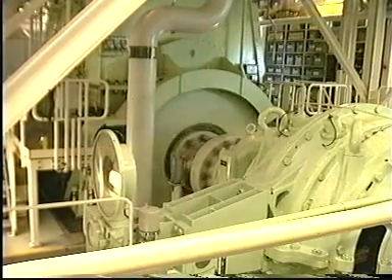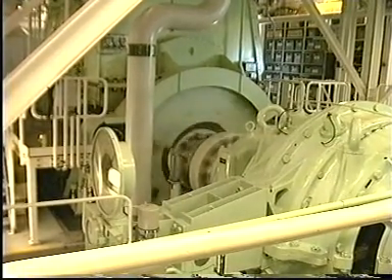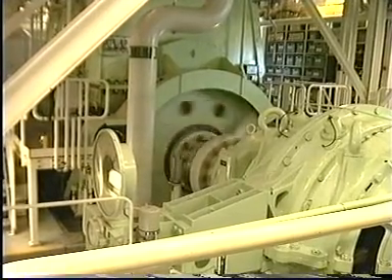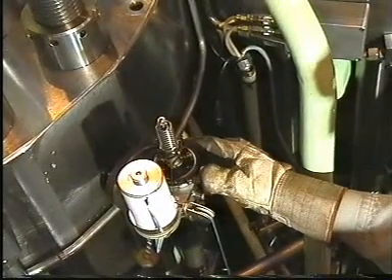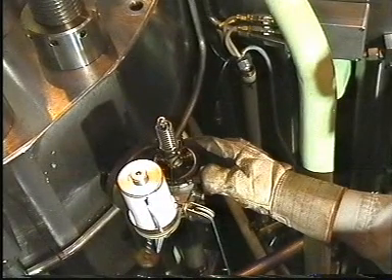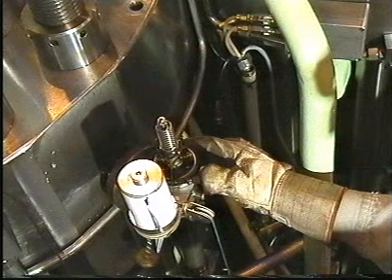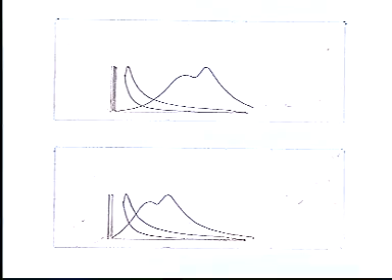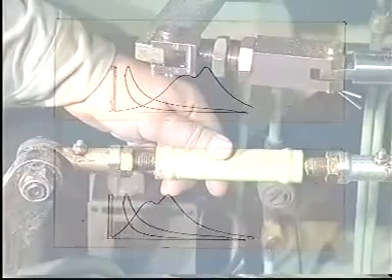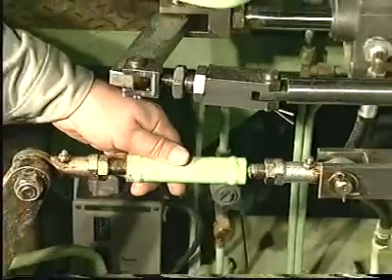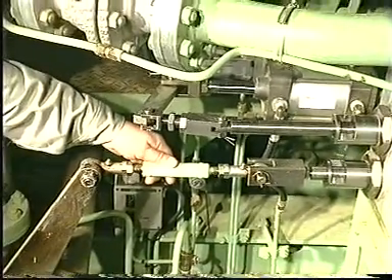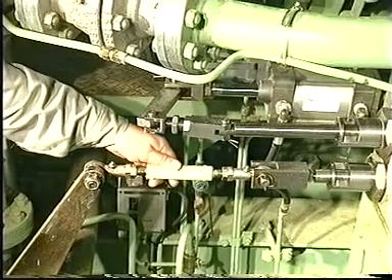Start the engine and run it up to a load corresponding to the brake point load, and hereafter to 100% MCR load. Use the indicator drive or PMI system to adjust the load so that it corresponds to the breakpoint load and 100% MCR load. Note down the fuel pump indexes. The mean indicated pressure of the individual cylinders must not deviate more than 0.5 bar. If the deviation is larger than 0.5 bar, adjust the load distribution on the fuel index rack of the individual cylinders.